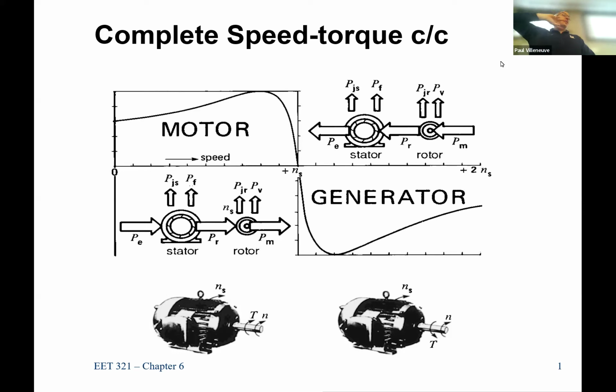So here's the biggest difference on synchronous machines versus induction machines. Synchronous machines can support a grid. They can run independently from the grid and they can feed the grid. AC induction machines cannot do that. You have to have some sort of voltage reference so that they can provide power. So another reason why you don't see very many induction generators is they don't do anything unless you have voltage.